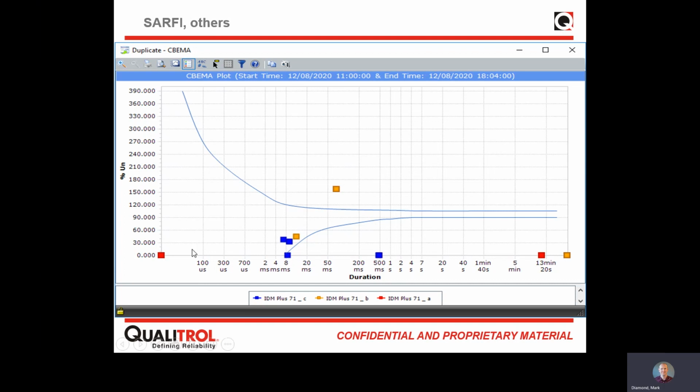So it defines the swell, the dip, and the time, and it becomes easy at a glance to see, well, okay, we've had 9 instances on this particular curve. 3 of them are compliant, one of them is just right on the edge, and the other ones, one swell was outside of compliance, and the other 3 were interruptions, which are outside of compliance. So these items here can then damage any electrical equipment, any electronics that's connected to that portion of the network. And it's just a really nice way of seeing at a glance what's going on with regards to dips, swells, and interruptions.